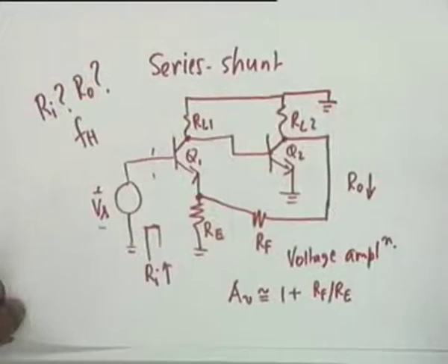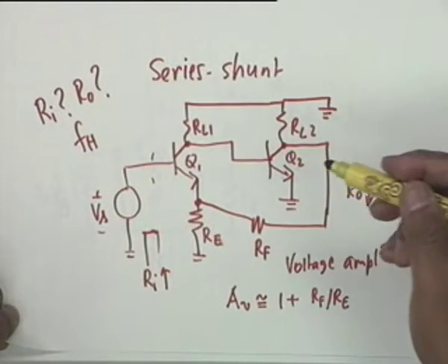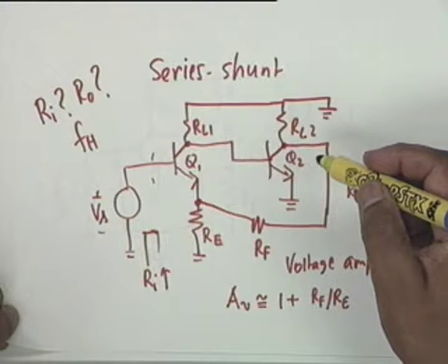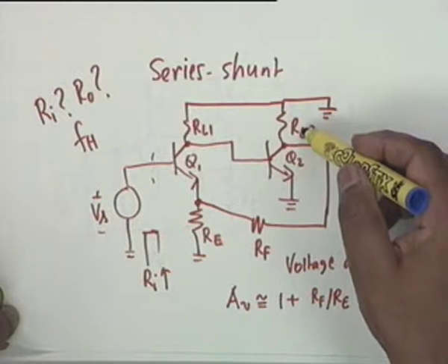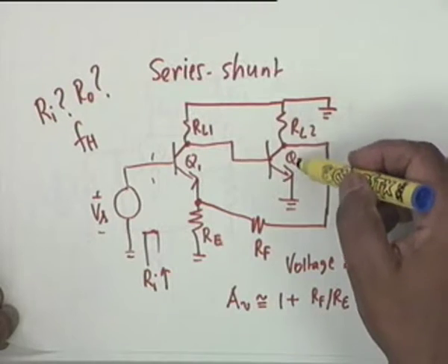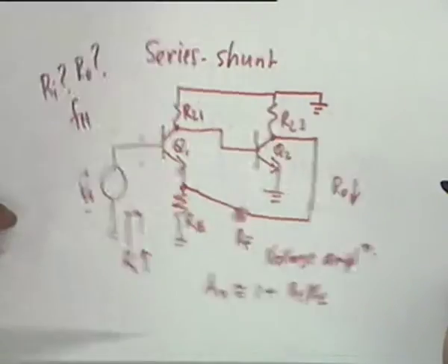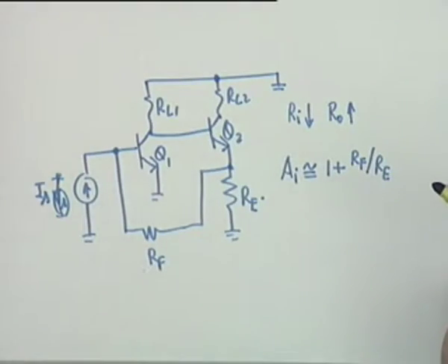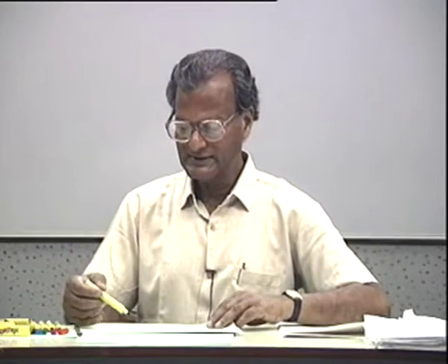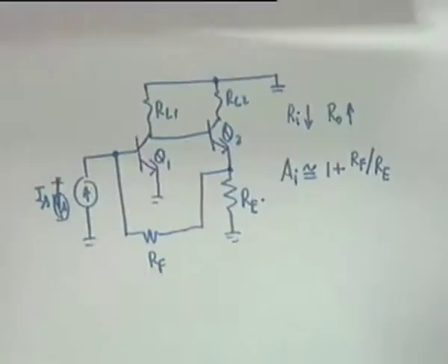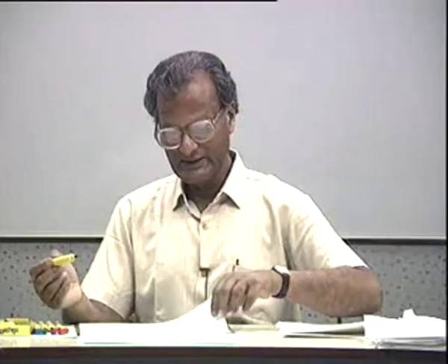Nevertheless, since this is the circuit that is mostly used, in order to isolate the load from the feedback circuit more effectively, one usually adds a third stage here, which is a common collector stage. Okay. And the total circuit then becomes as follows.